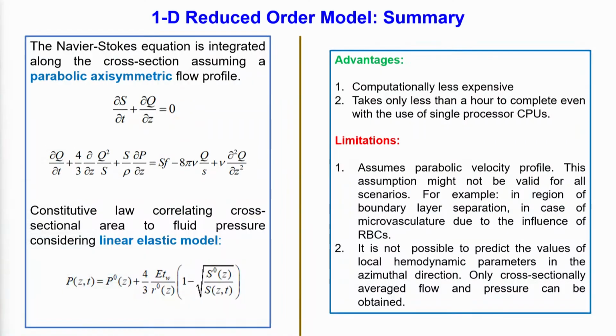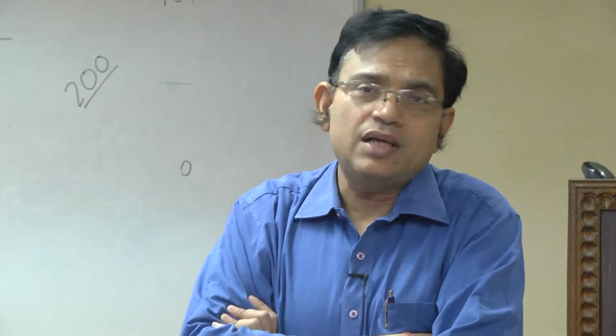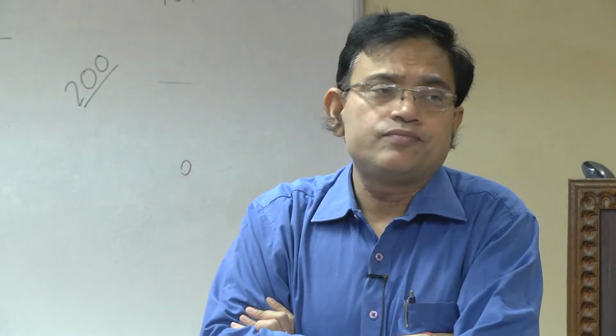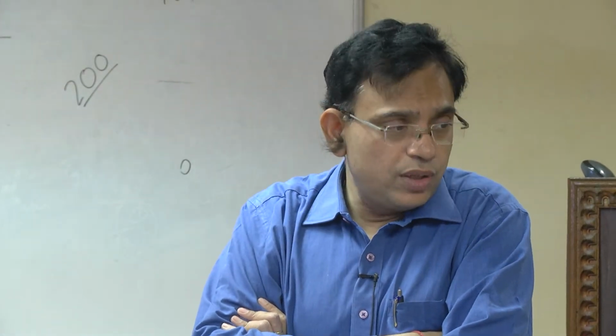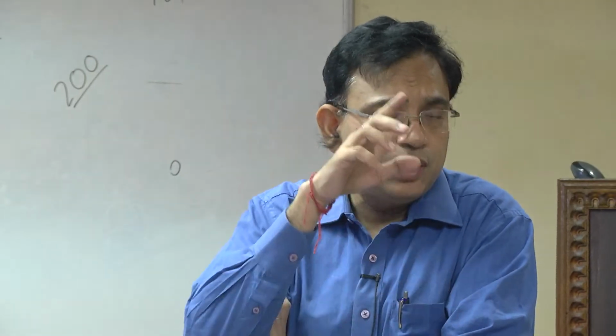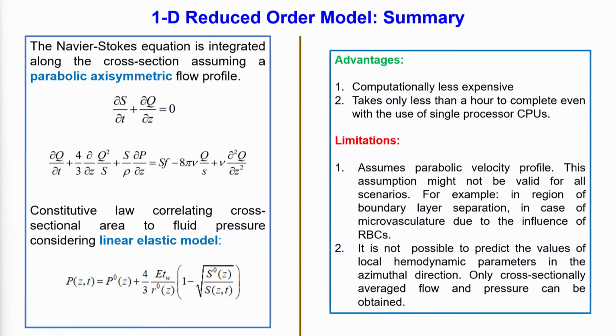Here the local radius itself is also a function of pressure, right. If you recall that microchannel problem, how did we do it? We applied the equation of equilibrium for the solid part of the domain, integrated it and got the displacement, and that displacement we related to the pressure. From there we got the expression, and displacement will be a function of the modulus of elasticity, etc. A similar thing applied here for a linear elastic fluid gives